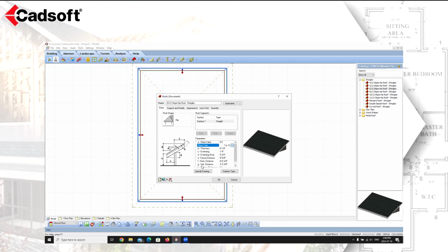Then we have the vertical distance, and that's going to be calculated using the G value here. And here we can see that the G value is set to, again, 3 foot 3 3/8. A lot of these values will adjust depending on the variables that you're editing. So some of these values may be adjusted automatically for you as you start to edit other fields. And that is by design. It's going to do all the math for you.